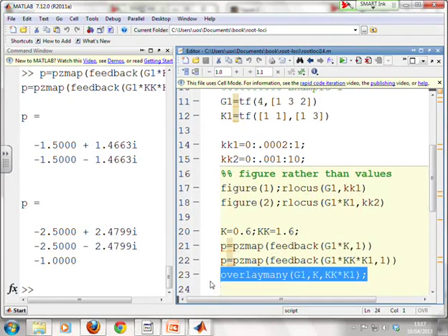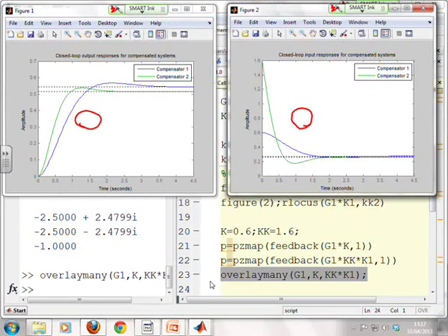And if we look at the step responses, there we go. I should perhaps get rid of those circles now. And what do you notice? You notice with the lead, this green one, it's got this faster transient, so a much faster response, but a bigger steady state offset. And how did I get this faster response? We go over here on the right and notice the input is much more aggressive during transients. Starts at 1.6 as opposed to 0.6.